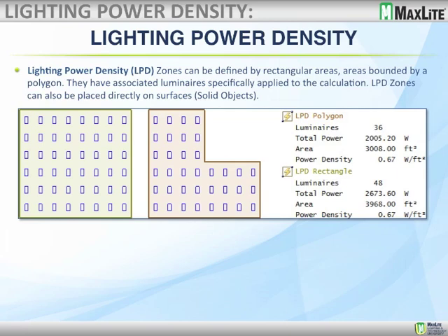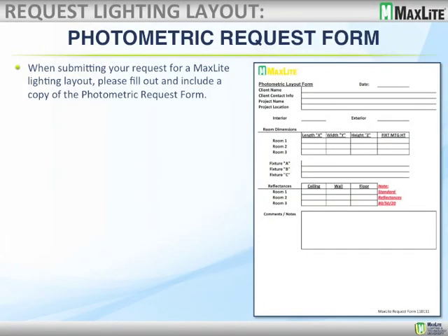Correct. There are many lighting software programs out there. A lot come from the manufacturers. We use independent lighting software, AGI 32, which the majority of people use, instead of something skewed more toward a certain manufacturer. So in order for us to use this, we have to supply our own IES files. If you're using a certain manufacturer's lighting software, their IES files are already added into the program, so they're already there.